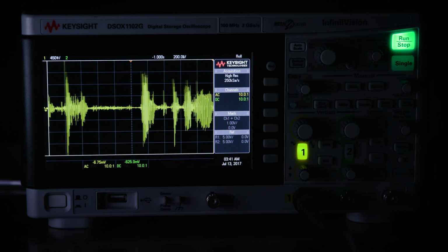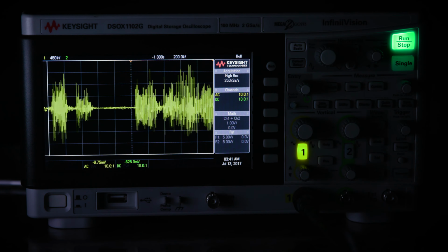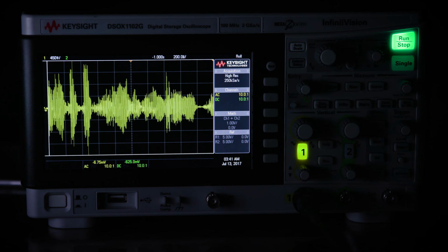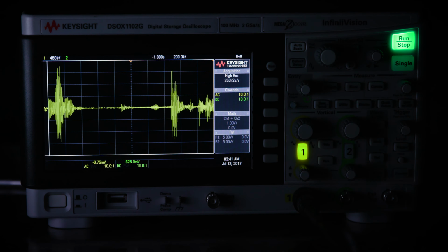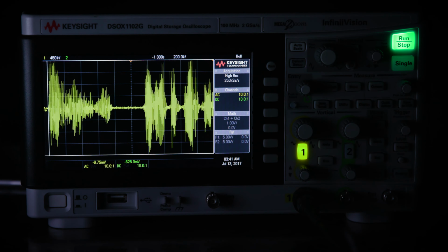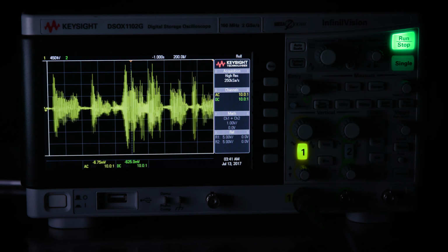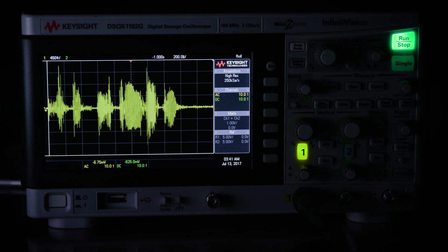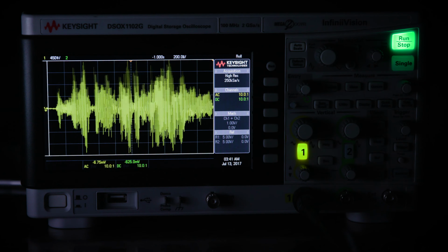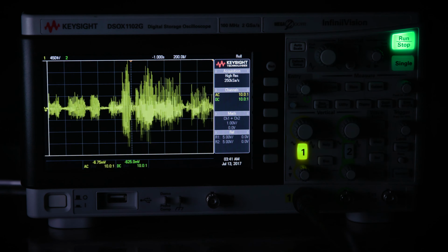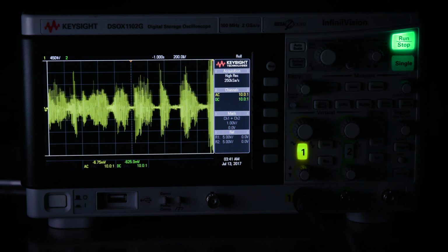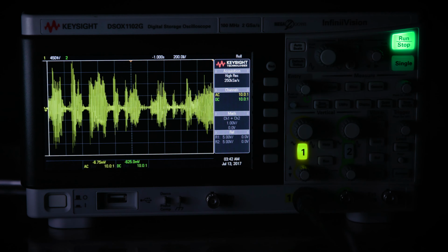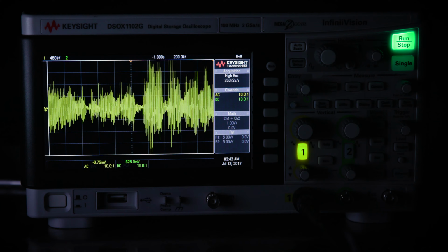But if you put that in an oscilloscope, you're drawing a trace a second across the screen, and all of a sudden there's a big spike in the middle of it, you can send a customer off for days trying to figure out what this spike is that only happens once in a blue moon, when it's actually his instrument, with seemingly no correlation to their system. And so there are some additional things besides the basic horizontal and vertical resolution that we need to watch out for on the instrumentation side.